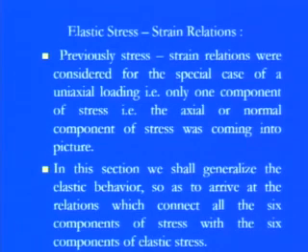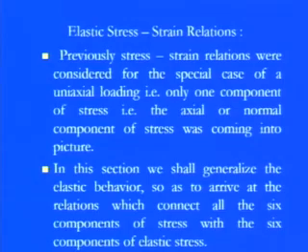Now come to the elastic stresses and strains. If we are talking about only the elastic region, what exactly is the relation between the stresses and the strain? Previously, stress-strain relations were considered for the special case of uniaxial loading, meaning direct stresses, in terms of pulling or compression, where the axial or normal component of the stress came into the picture. We are considering the elastic limit first, and that the load application is axial, with no eccentricity and no parallel forces in that particular component during the load application.